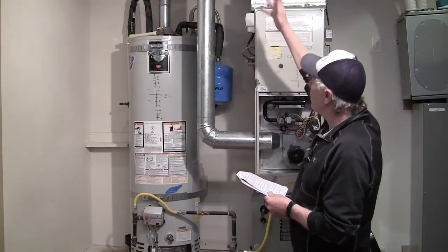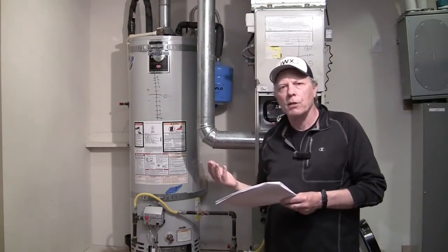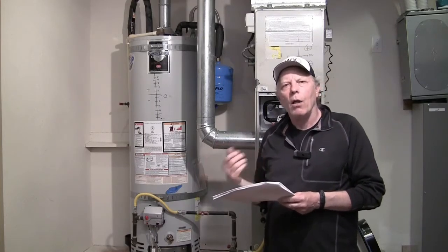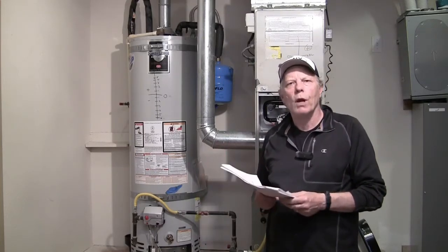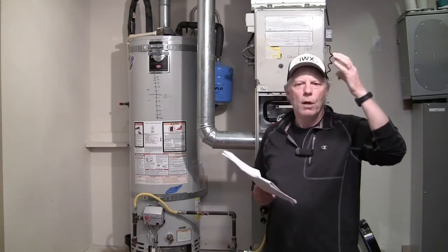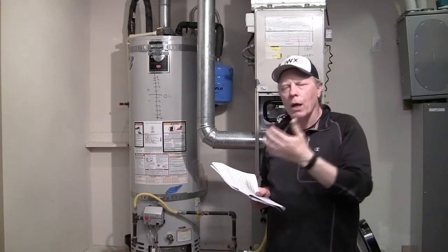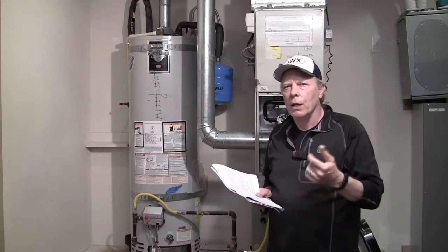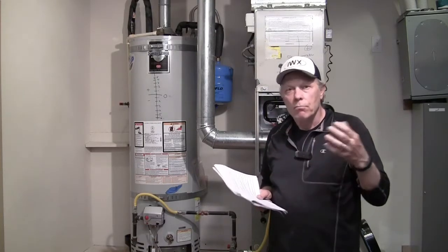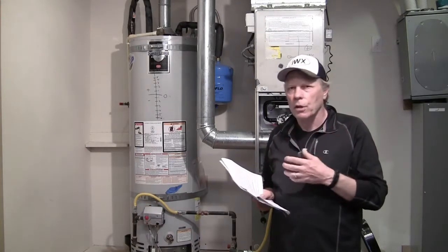I can see from here that it looks fine as it goes through up to the attic. In other parts of my inspection, I'll be in the attic and I'll take a look at the flue up there, and I'll also take a look at the flue when I'm outside looking at the roof. I want to make sure there's a cap on the chimney that's not damaged at all and not corroded too much. And then in the attic, I want to make sure that the flue system is together, connected, and that there's not a bunch of insulation against it.